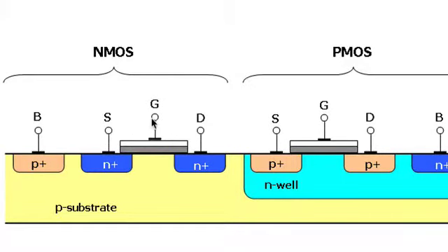Previously, we had the gate and body terminals, and we added a source terminal. To complete the structure of the so-called N-channel MOSFET, we'll add a second heavily doped N-type region with a P-type substrate to form the NMOS transistor. You can also have a PMOS transistor where all the N's and P's are swapped.